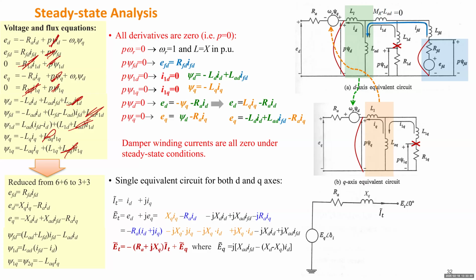So if you took 421 or any other power system analysis for static conditions, you might have learned this equivalent circuit. In that equivalent circuit, usually for the reactance, we use a notation which is XS. We call it a steady state reactance. So from this circuit now, you know that reactance has to be XQ. So it's not XD, it has to be XQ. For a round rotor generator, XQ and XD will be very close, so you can use either one.